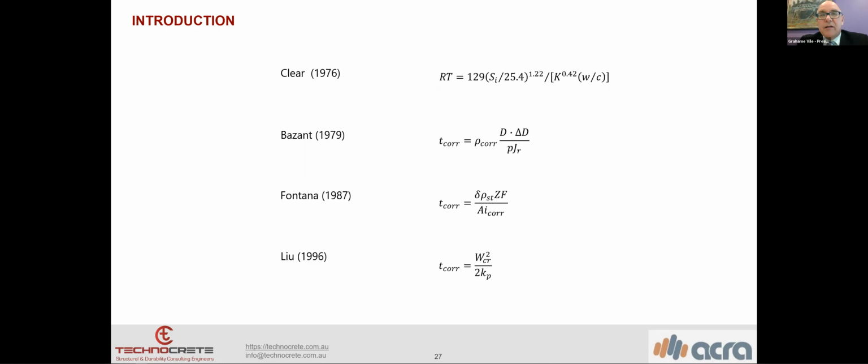If the aim is to avoid inspections, then brush and whatnot can come up against the abutments fairly easily in a 5 to 10 year period. So yes, if the fire can reach any type of structure, we have to do a post-fire damage inspection and a structural assessment. Yep. And then, yeah, it's good.